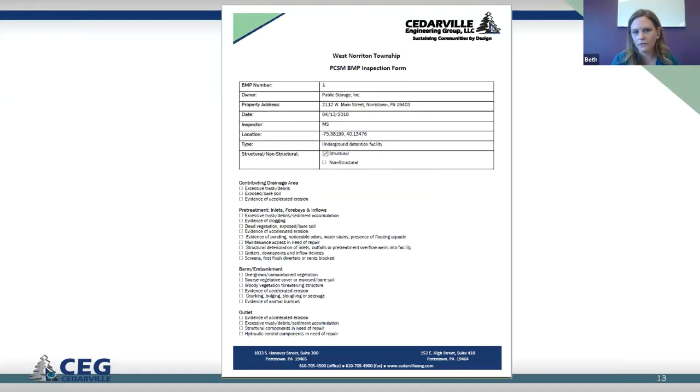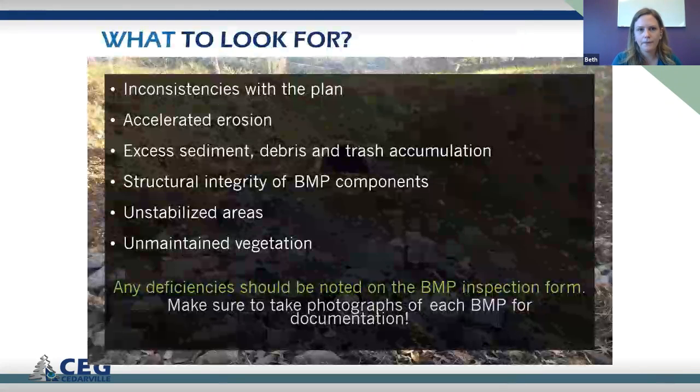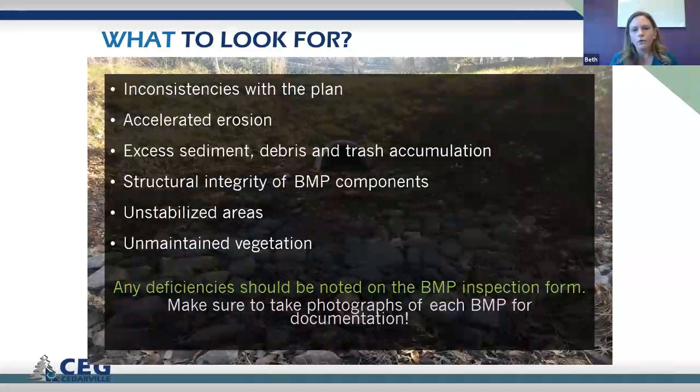And this form allows you to attach photos to it. It accesses your camera. And then Survey 123, which is an Esri product, will convert that into a traditional form as well to document your inspection and your site visit. And it also attaches the photos like that.